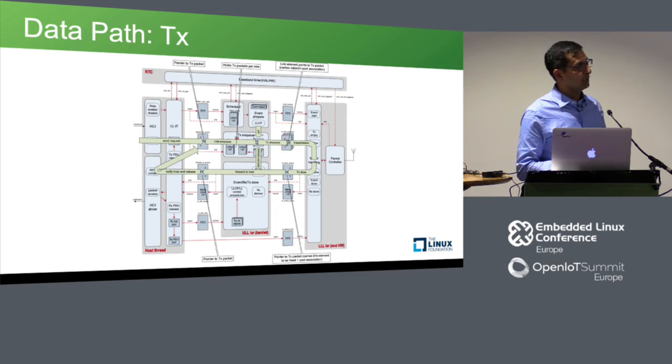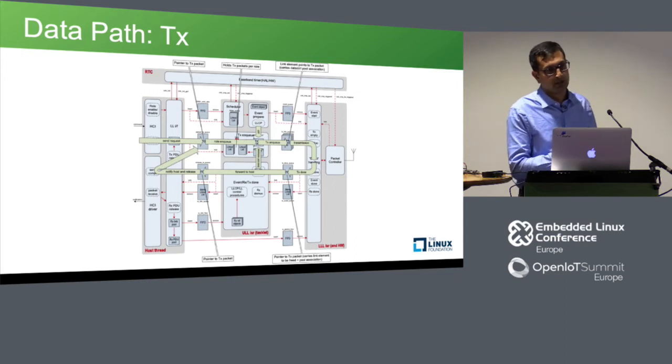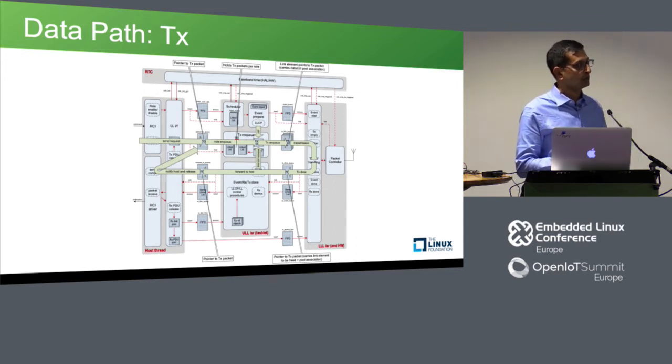And when a connection event occurs, only that packet is utilized by that event, transmitted, and then comes back in a FIFO here, because the num completes would at max be 10, because that's what was configured in Zephyr, that you would like 10 TX buffers.